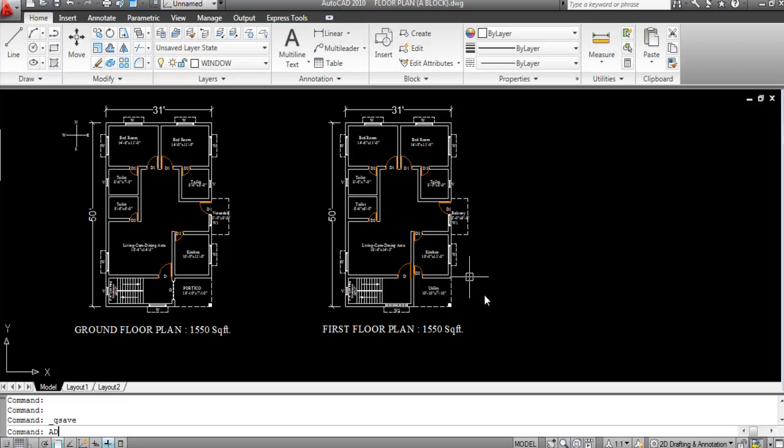Okay, so here add center is the command to open the design center and shortcut key is ADC. You can also open design center by pressing Ctrl 2. By pressing Ctrl 2 key on your keyboard, you can also open. Just press the Ctrl key and 2 key simultaneously, to get the design center interface. Okay, so I'll just press Ctrl 2 to get the design center interface.